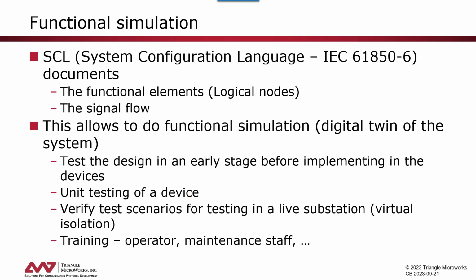Another example is unit testing of a device. Let's take the use case that you have a device in your live system that has failed. You need to replace it. So you get a replacement IED, you have to configure it, and you want to be sure that the configuration is really working as expected, that you configured it right. So before you put it in the real system, you can put it in a test bed where the remaining devices are functionally simulated and interacting with the physical device that you want to verify the communication.